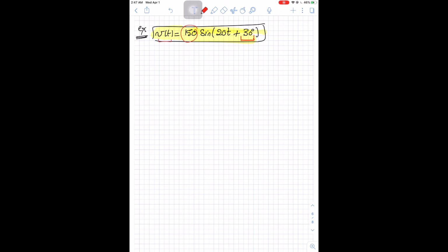This means that your voltage will be zero not at t equals 0. It will be 0 when this angle omega t equals 30 degree with negative angle. So your wave will be 0 at negative 30 degree. So if we need to sketch the sine wave, here is negative 30 degree, and your wave should be starting with 0 at negative 30 degree. Then this will be your wave.